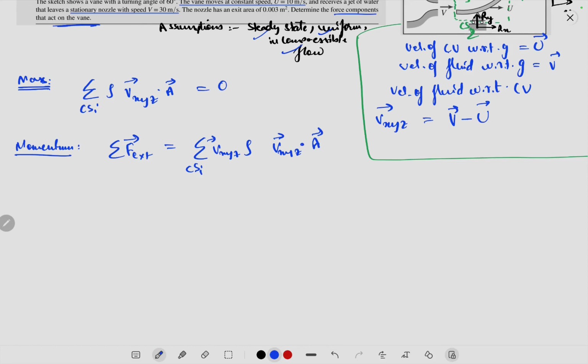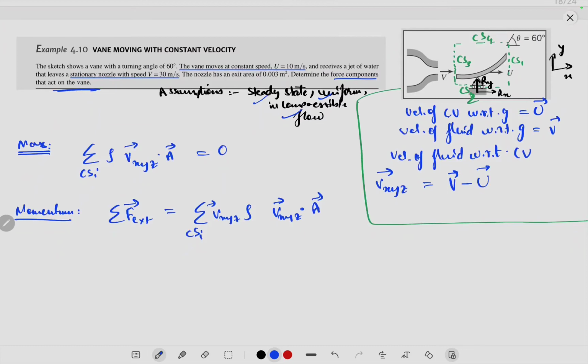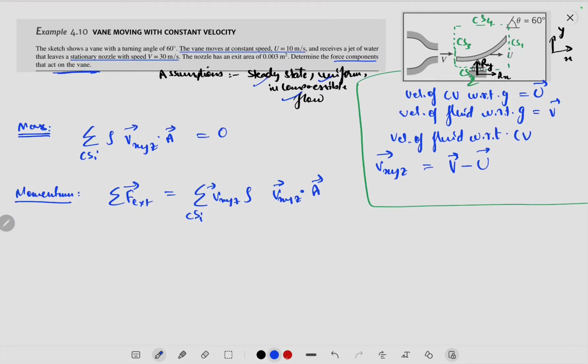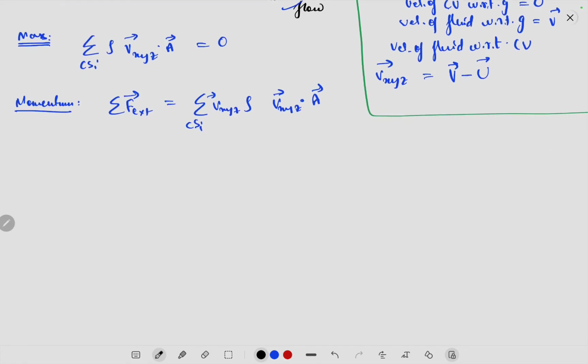You can also see that a gravitational force is acting downwards, equal to mg, where m is the mass of the total system. Now since the unknown forces for this problem are Rx and Ry, which are directed along different axes, let's break this equation into two orthogonal axes.